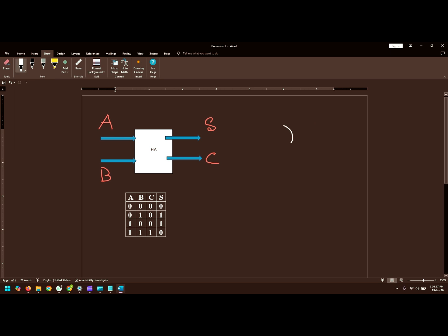First, I have to use the XOR gate. You can write the XOR gate with two inputs given. Here we have one AND gate. The AND gate output becomes the carry, and the XOR gate output becomes the sum. A and B are the inputs, and these are the gates. So in this one, now we'll go to